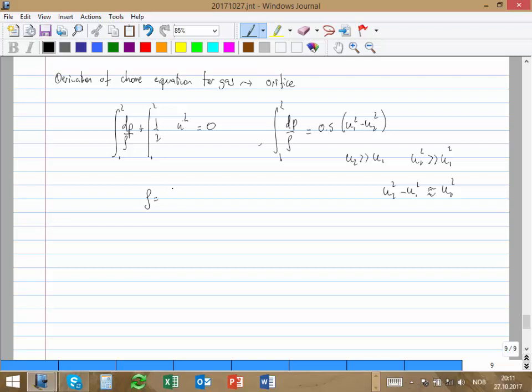That's one assumption. Then the other assumption I make is that the density, if you remember from the real gas equation, is P over Z R molecular weight and T, right? So I can use that equation for the density. But also we know something else. We have all of these choke models. So this is the momentum equation for the gas.